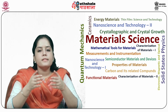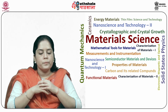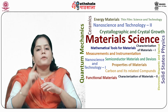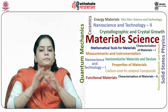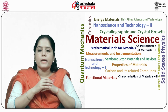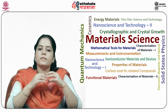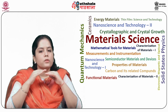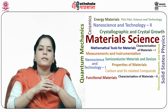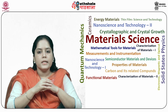Fabrication of Enose. Now there are various steps which are used to fabricate the Enose, and these steps will be discussed sequentially. First is cleaning. First step towards the fabrication of microelectronic devices is wafer cleaning. So the silicon needs to be cleaned thoroughly following the standard process of cleaning, including RCA1, RCA2, and Piranha Cleaning.